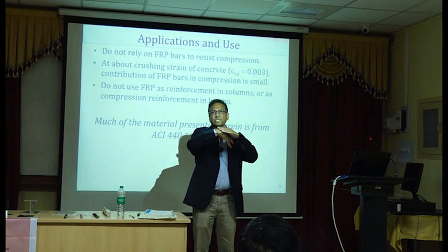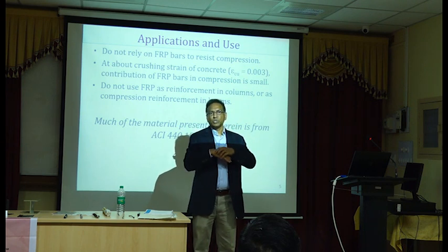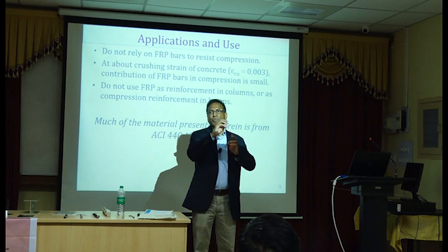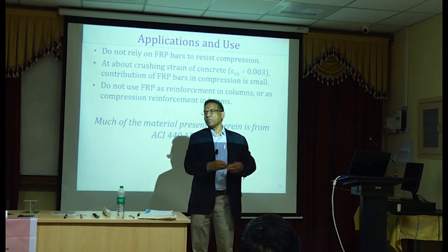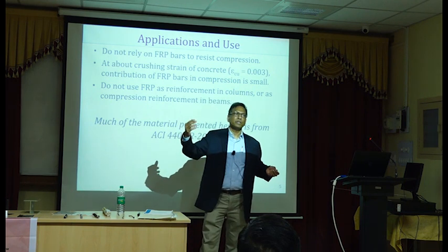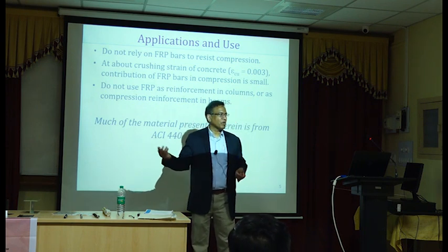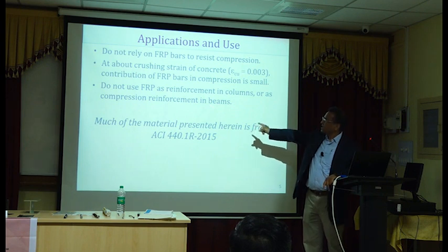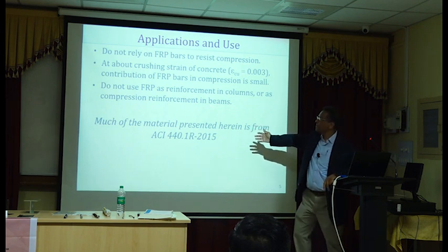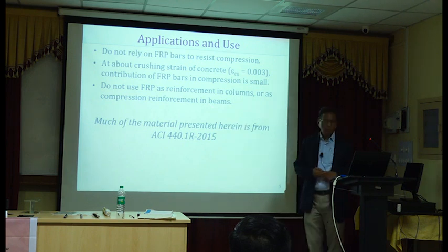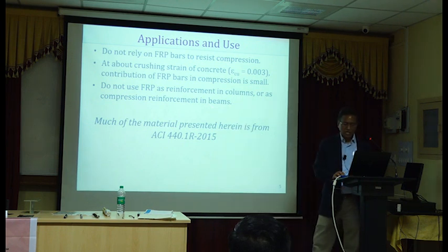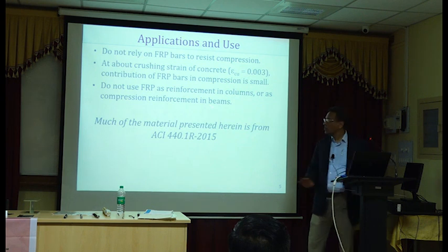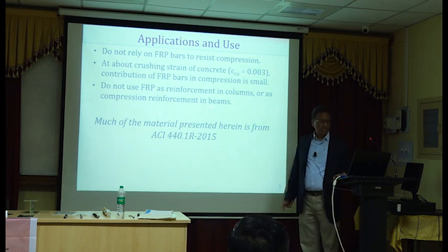So the top is actually exposed to larger corrosion effects. So you may have epoxy coated bars at the top. At the bottom, it's not really a problem. So they use normal black bars. That's mixed mode is possible. You may try to use that kind of approach even here if needed, because really you cannot use FRP bars in compression regions. Okay? So much of the stuff I am going to discuss is based on ACI 440.1.